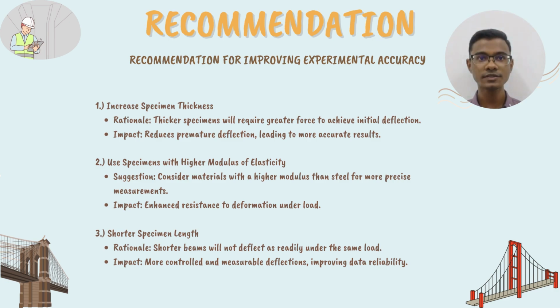Next would be the use of a specimen with a higher modulus of elasticity. This suggestion considers materials with a higher modulus than steel for more precise measurements. The impact would be enhanced resistance to deformation under load. The third and last recommendation would be a shorter specimen length. Rationally, shorter beams will not deflect as readily under the same load or with higher loads. The impact would be a more controlled and measurable deflection, improving data reliability.